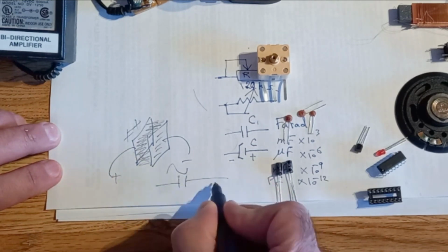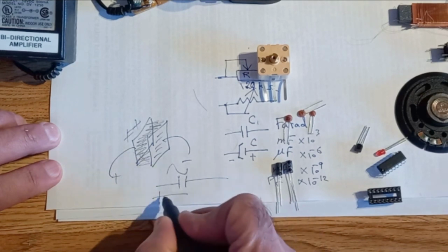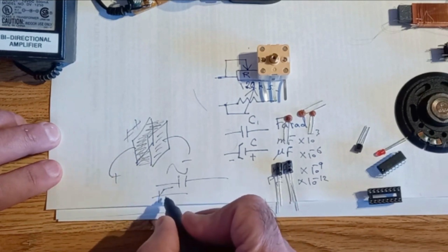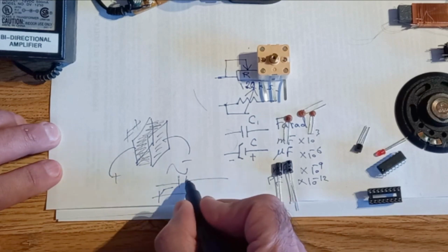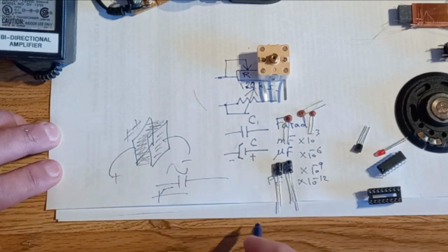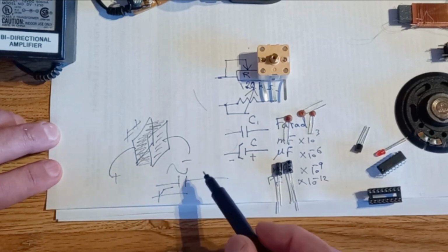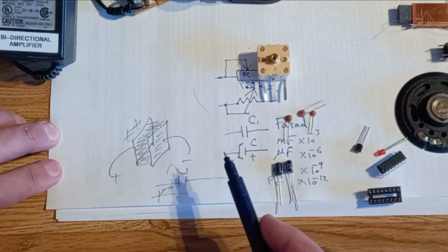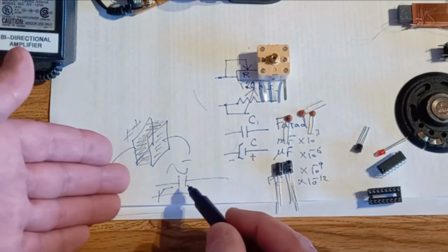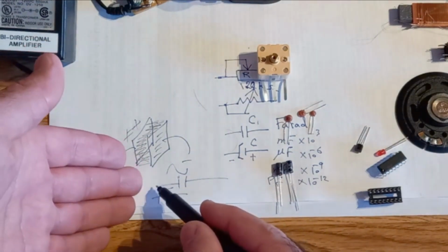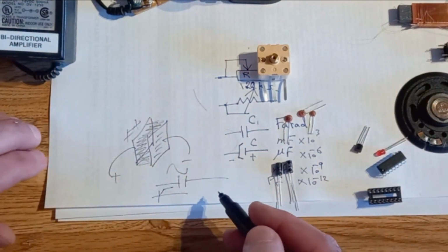AC passes through a capacitor, but DC, that is a fixed voltage, which we discussed in the previous module, doesn't go through from one end of the capacitor to the other, which is why you use these for filtering. By filtering, I mean you remove unwanted noise from one end of the circuit to the other end.